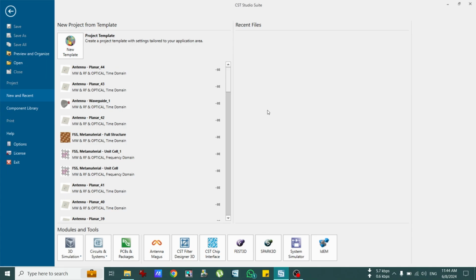So these microstrip lines are required there for the transmission of RF signal from point A to point B, and it is critical to have good impedance matching from point A to point B and minimum standing waves to ensure efficient transmission of the signal and low noise.